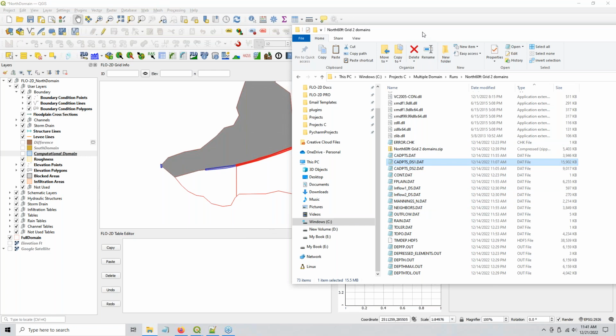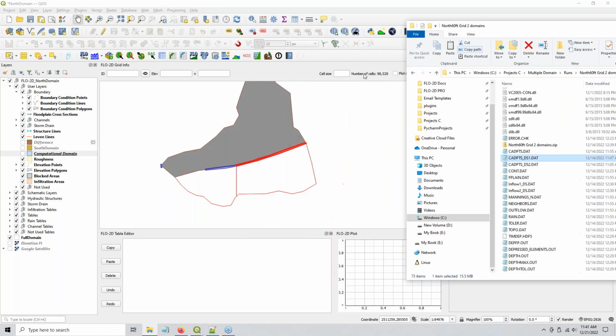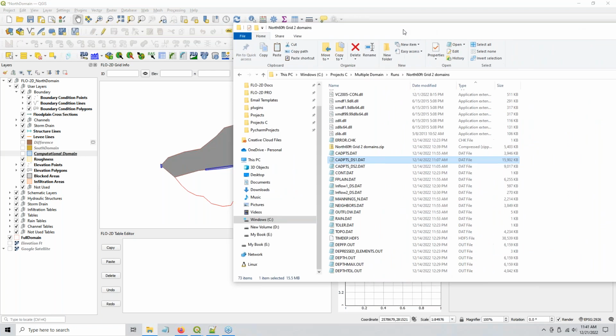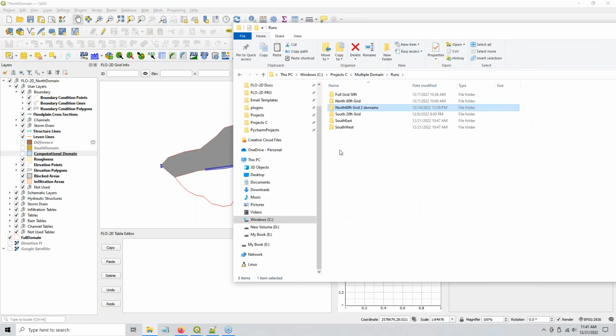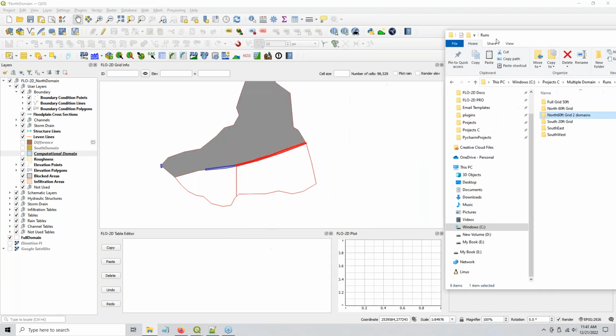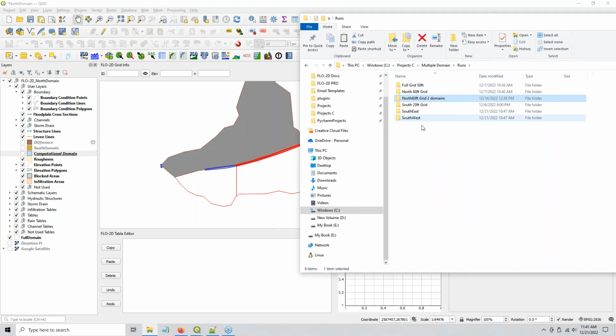So then you can use these two inflow nodes in the downstream model to set those up. Now, unfortunately, this one's kind of ridiculously complicated because of this boundary right here. So you've got to be a little bit careful with it. That's why I tell you, don't try to meld or mesh a model on two connecting domains. Just use one, but then I wouldn't be able to show you these other processes. So that's why I did it this way.